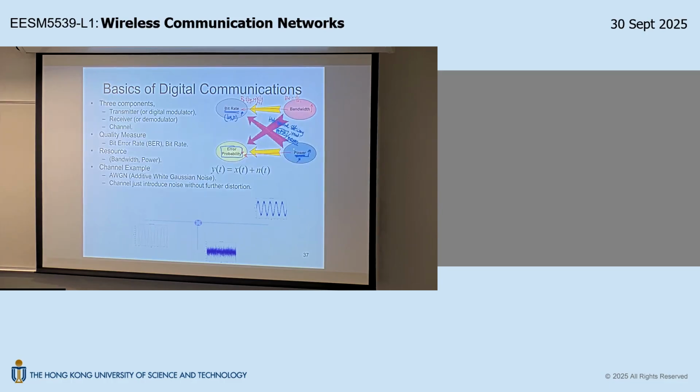So that's why in practice, you will see people using BPSK, QPSK, 8PSK. But when you go for 16, not many people will use 16 PSK. Most of the time when you come across 16, they will go with 16 QAM and then 64 QAM. So MPSK is one family, MQAM is another family. These two families aim to achieve high spectral efficiency, but QAM would be more efficient than PSK. Is that okay?